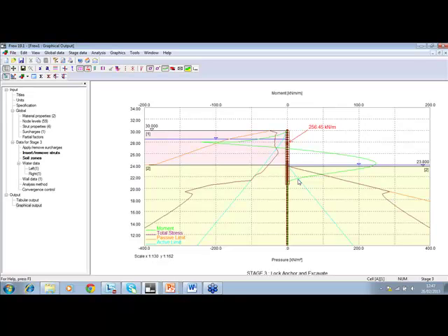You will also notice here that the pressure is at passive limit. So if this is an SLS analysis, you might be thinking, maybe that's not great because you're going to get quite a large deflection, which you are getting here. So we've got a larger deflection because we've got our pressure coming at passive limit.